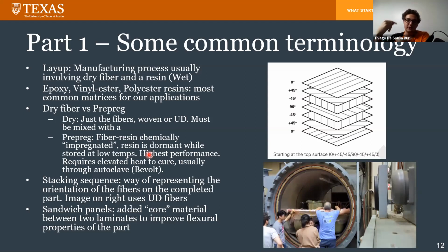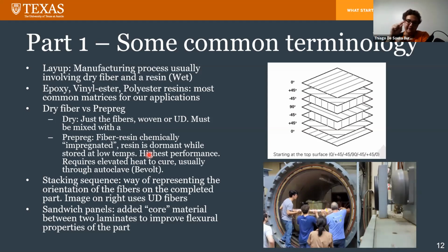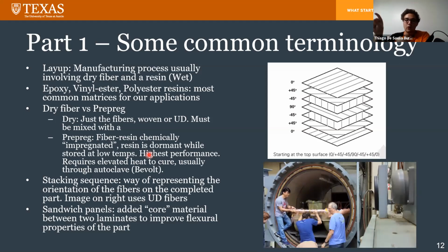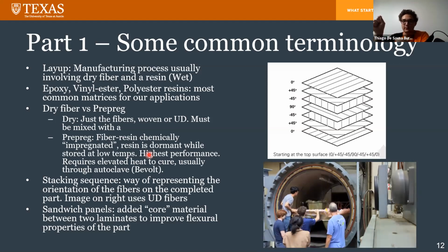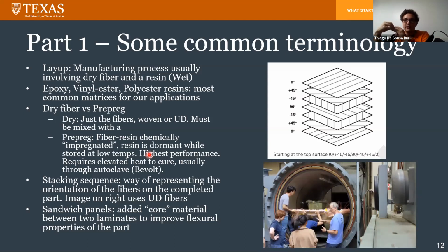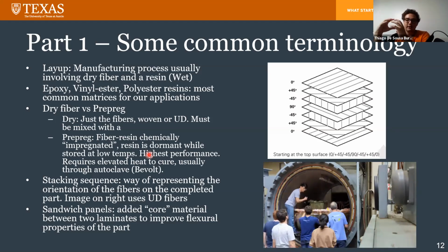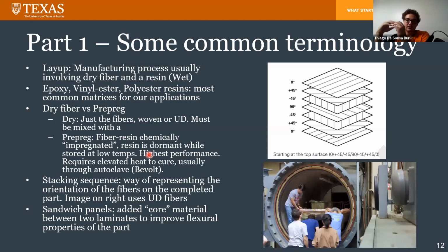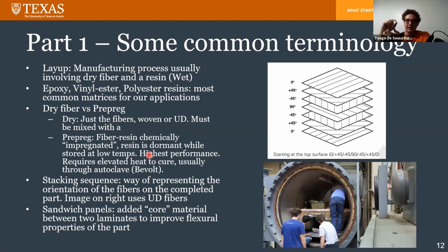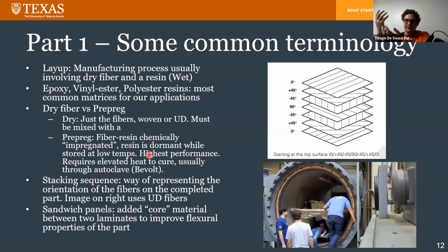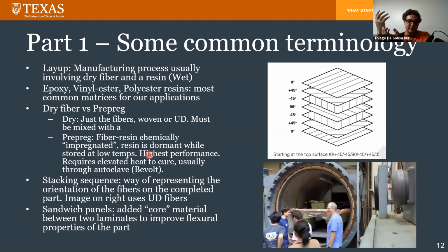So what we do is we increase the moment of inertia by adding that foam core, or a core in general. Honeycomb is another commonly used one. Essentially, we're not really adding to the property. Or I mean, we are adding to the property, but we're not changing the chemistry of the composite. We are simply making it thicker so that it's harder to bend. It's like the dumbest thing, but it works so well. So we keep doing it.